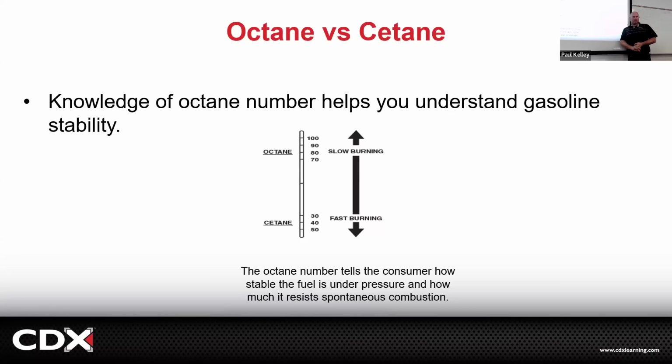You no longer have control of that combustion. That'd be pre-ignition specifically. So if you get pre-ignition, now all of a sudden we got this flame front starting because the fuel ignited itself on compression, kind of like a diesel. Then you got the spark plug, and the spark plug's like, all right, I've waited for this moment. Spark it. And it's like, dude, we're already burning. This is out of control. You're losing control of that engine. And you're also going to probably have those flame fronts colliding, and that gives us some of our sounds of spark knock or detonation, these types of things, right? So that's a big problem.